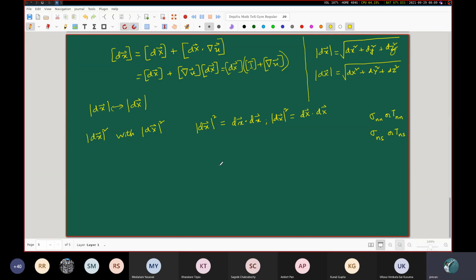Here also, in this topic of transformation of strain, our idea is similar. We are talking about these deformations in terms of this general vector dx, d small x vector, d capital X vector, but we want to determine the nature of the deformation along a particular given direction. This is what we want. So suppose we have a given direction, given by the unit vector n. We want to find out what the strain is along that direction, because if we are able to do that, then in a very general way we might as well be able to obtain these rotated versions, like going through theta and then obtaining the expressions. So we'll see what I'm talking about.